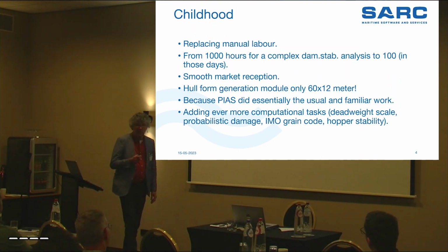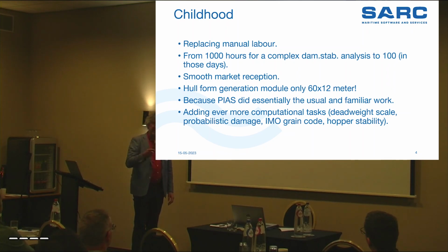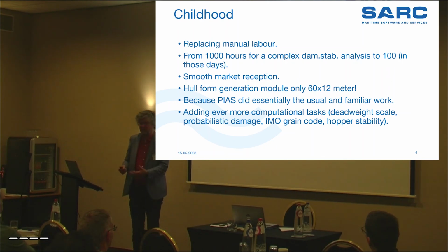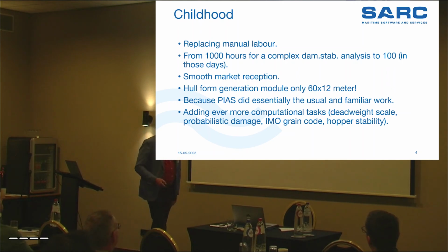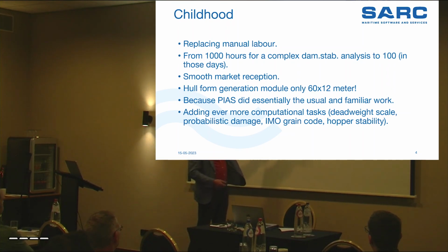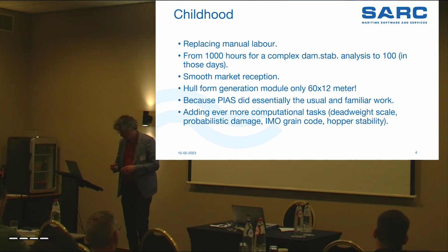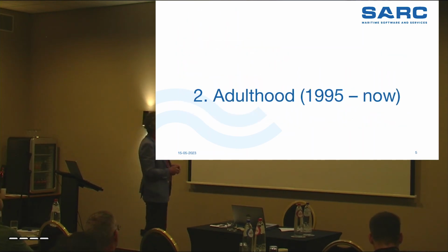And why was that the case? Not that the guy had trust, but why this smooth market reception? Because PIAS did essentially the usual and familiar work. It did the same as what people were doing by hand, but then on the computer. So that was the beginning. After that, it was quite easy adding ever more computational tools, such as deadweight scale, probabilistic damage stability, grain hopper stability, well, you know the list of modules in PIAS, most of which were conceptualized in those days.